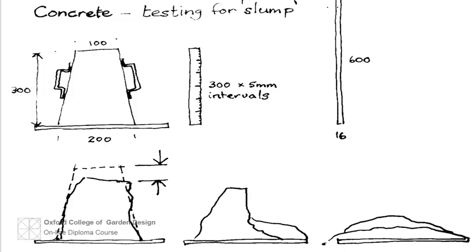The surface is smoothed and compacted by firm troweling using a wooden float. The lining should then be cured immediately under plastic sheeting for 3 days before filling with water. The water must be drained 3 or 4 times at weekly intervals until the alkalinity of the surface cement has decreased enough to permit planting and perhaps for fish to be introduced.